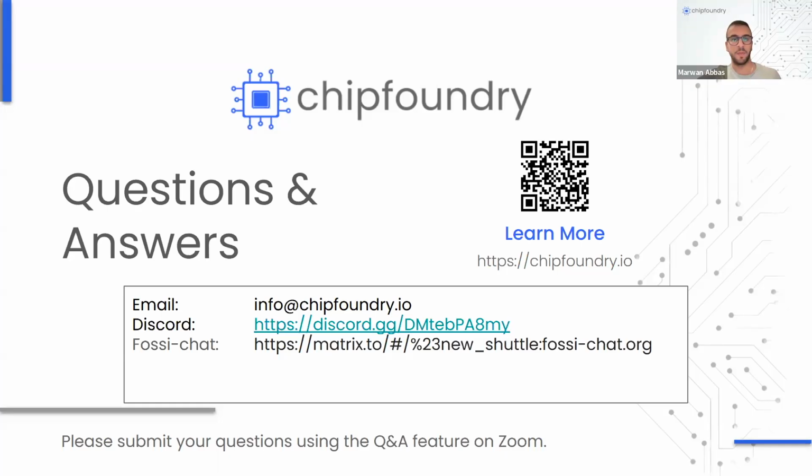Okay, good. Can the read circuits and ADC handle multiple bits? Theoretically, yes. If the user wants to play, they can try, but they are designed for only binary operations. Just to say that the sensing margin might not be that great for this, but they can still have some flexibility to play with it.